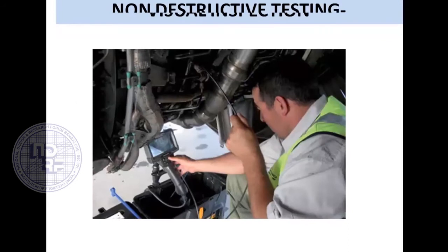First is visual inspection. Visual inspection is nothing but using the naked eye, checking the aircraft, checking any component for any failures. An aircraft comprises so many things: the rivets, pipelines, the skin. Any damage which is accessible to the naked eye can be seen using a torch. In case there are some inaccessible areas, use a special equipment called the borescope, what you see on screen.